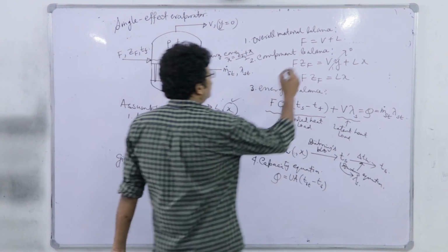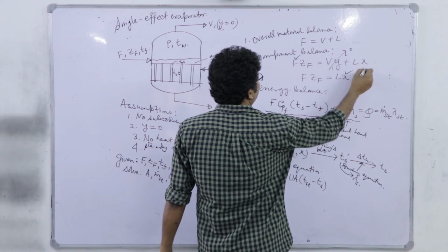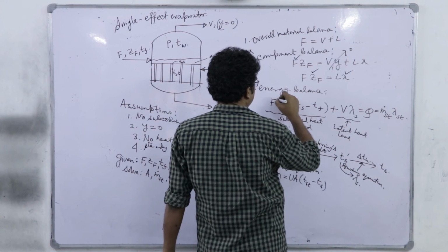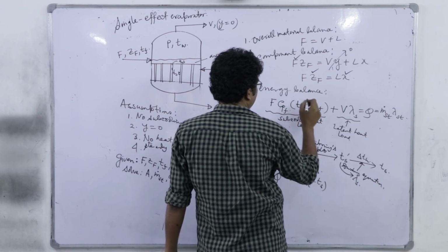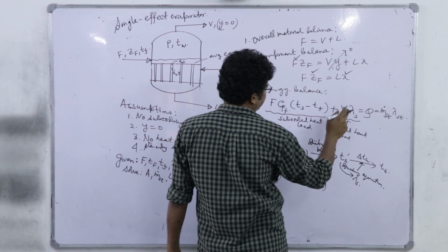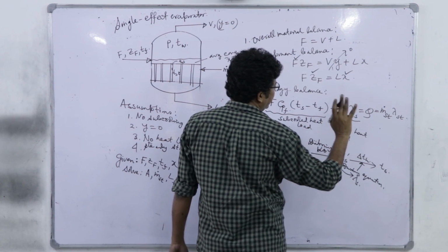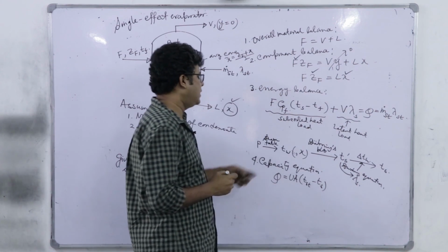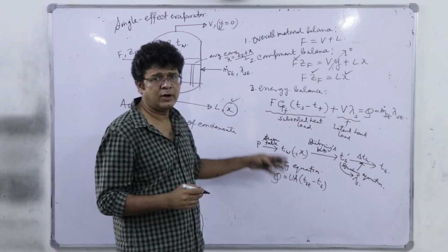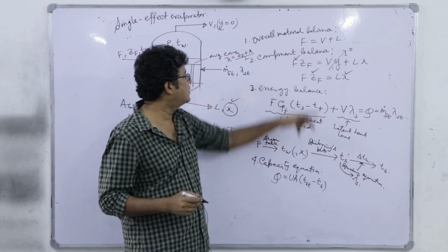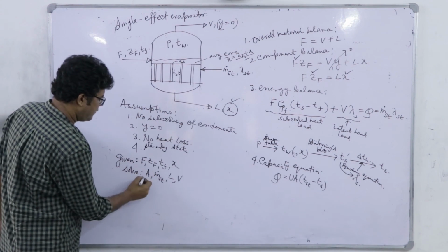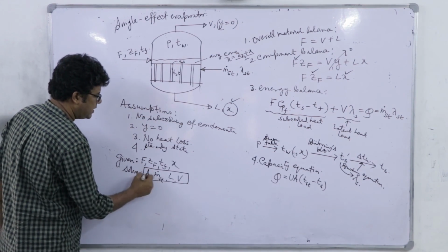So we know F, we have got ZF, we know X, right. Cp can be calculated, Ts calculated. So if we simply eliminate this Q, right, and here we write m dot st into lambda st equal to this, we have 1, 2, 3 and 4 equations and we have 4 unknowns to solve, right.